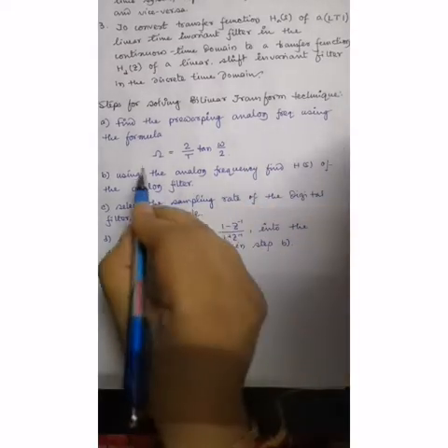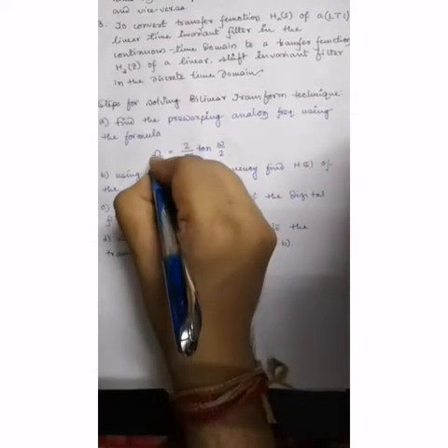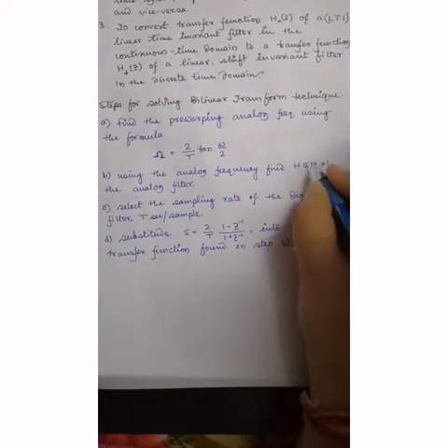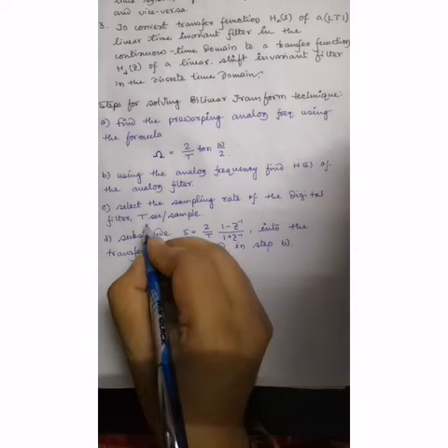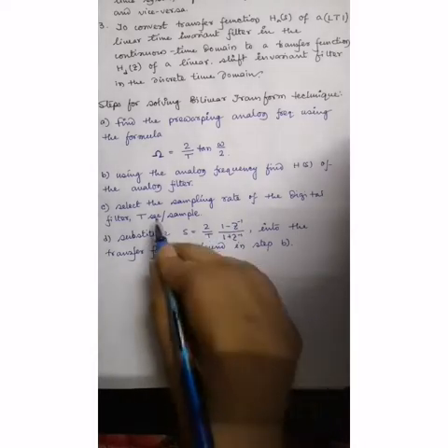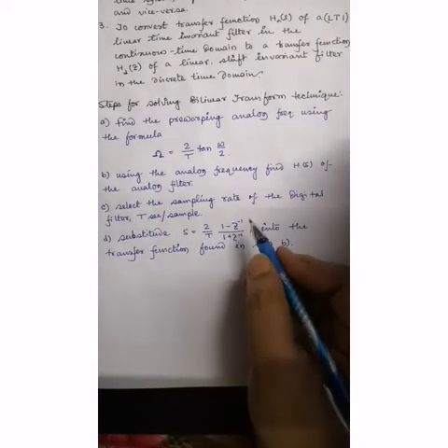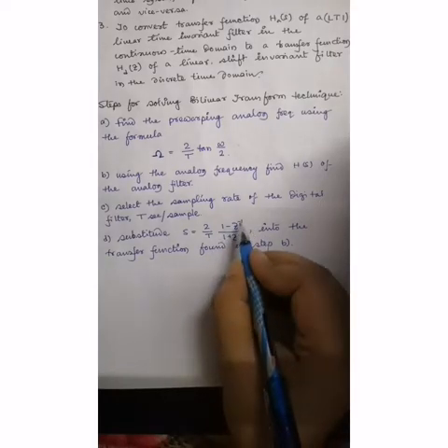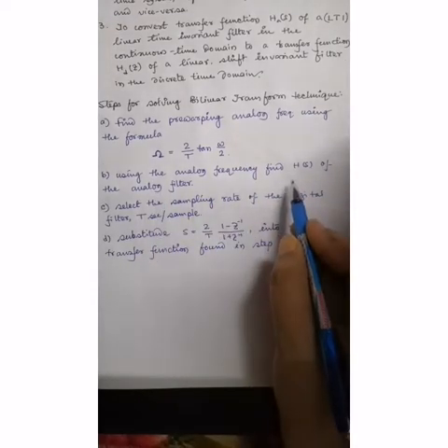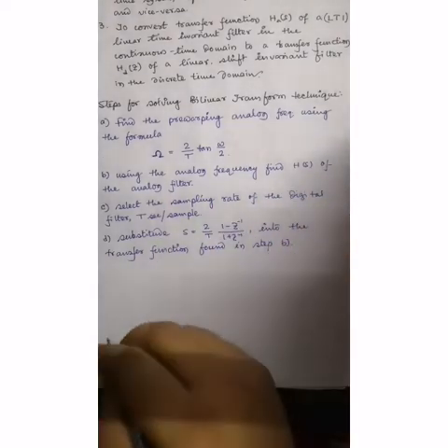So first step is we have to find the analog frequency using the formula. That means the first target is to find the H(s) value, and for that we have the sampling rate, that is T, which is mentioned in the question. Then substitute s as this value, 2 by T into (1 minus z inverse) by (1 plus z inverse), in that transfer function. That is step number 2. Then we will find the answer in H(z).